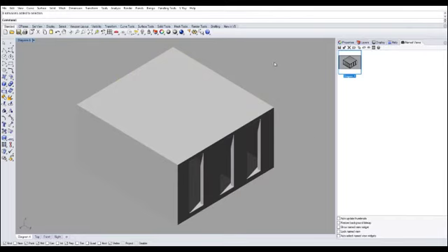Now we have to do a couple of initial steps in V-Ray settings for you to be able to properly render this. So your V-Ray settings are listed under the settings option, which looks like an asterisk. If you click on that, this menu pops up. Only two things you have to memorize for this particular setup, and that's all you need for the rest of the semester, and that is your quality set from medium to very high, and then your global illumination, make sure it's on, which is the default. And then if you expand that menu, there's an option called ambient occlusion. You also have to have this one turned on.